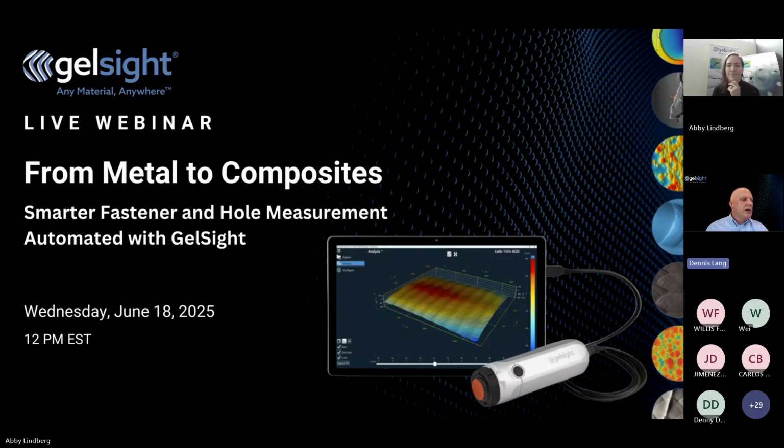Of course, moisture traps lead to corrosion, and this is something GelSight spends a lot of time looking at in the field. Corrosion of all different kinds, but certainly corrosion in and around the fastener. When we think of fasteners that have been recessed too deeply, they have sealing defects, and then you start putting these into scenarios where you have dissimilar material sets, that galvanic corrosion can lead to very problematic things that aren't expected within the design parameters of the system.